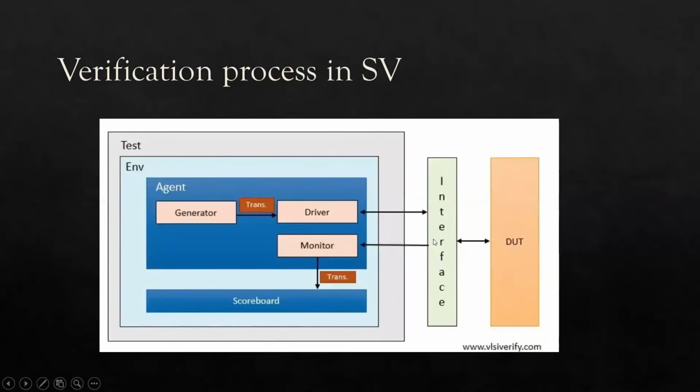Okay. Through this, it will go to the monitor. Monitor means it will just monitor whatever things are coming from the design to your test bench. Once the sum and carry value is received, that will be transferred to the scoreboard. Scoreboard is nothing but a comparison: whether the correct output is coming from the DUT or not. These things and these logics will be there on the scoreboard side. Okay. So this is how an entire test bench is built in SystemVerilog to verify a design.